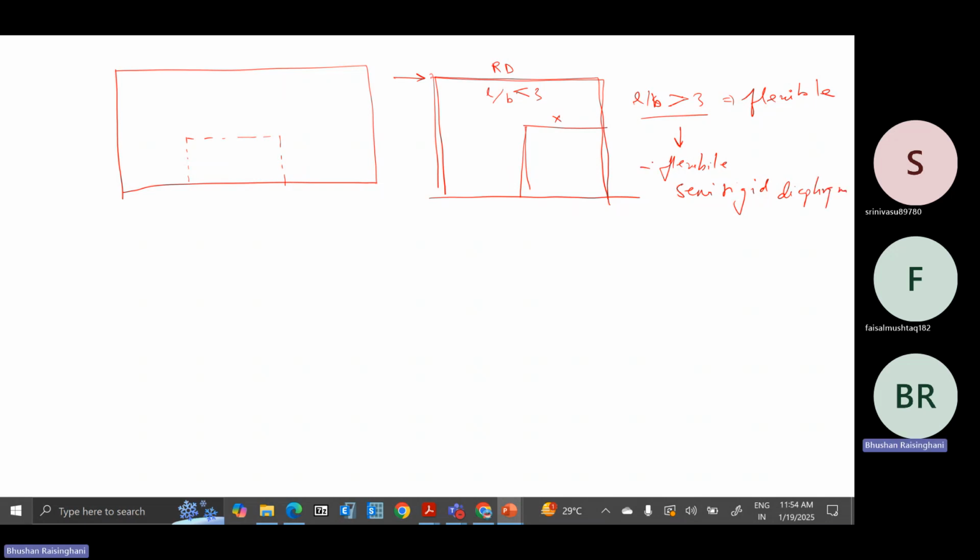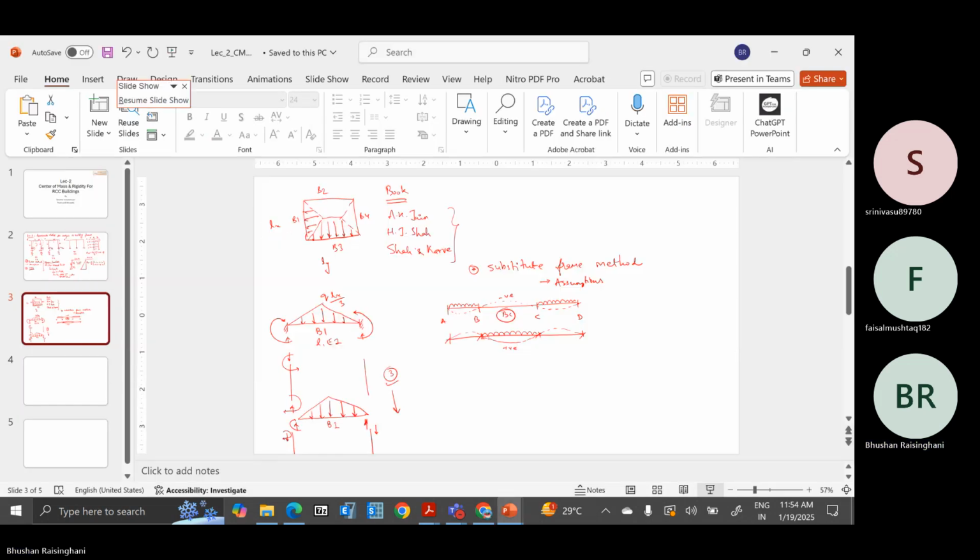So you have to first understand what is the given slab arrangement, what is the aspect ratio in plan for the floor and also for the building, both aspect ratios. So either the floor can be flexible or the building also can be flexible, right? So based on that, you have to check this requirement.